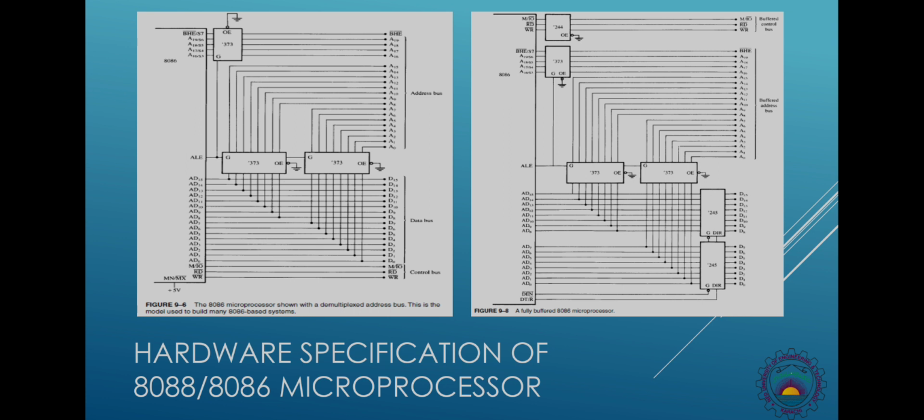The third latch is connected with the address status multiplex bus A16 to A19. So the same is the case with the third latch. OE is grounded and G is connected with the ALE pin. So whenever there will be an address at these pins, the latch will be enabled and the output will be having the address pattern A16 to A19, and BHE bar is also demultiplexed from status pin S7 by using this latch. So the BHE signal will also be demultiplexed.